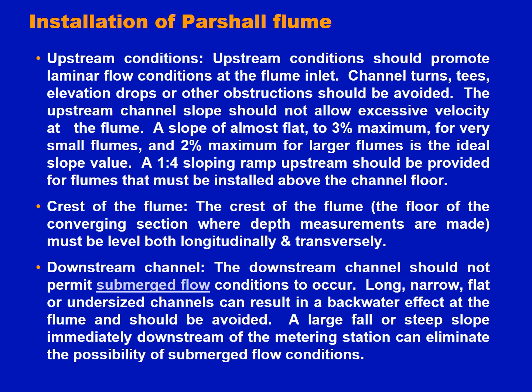Now, regarding the previous discussion about the flume and how we can measure the discharge: installation. Suppose there is a channel in the field and I want to measure the discharge of this channel. In the entire channel, where and how can we install this Parshall flume? First is the upstream condition, then the crest and the downstream channel.